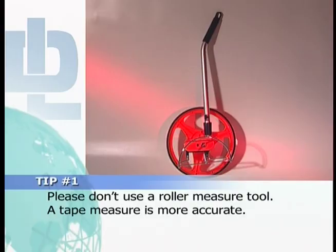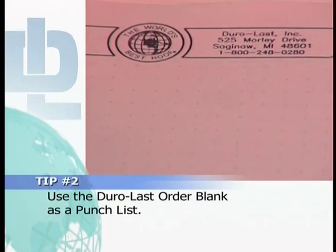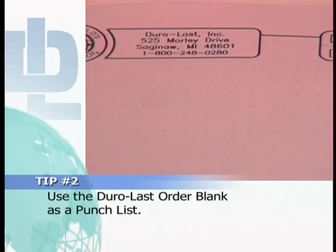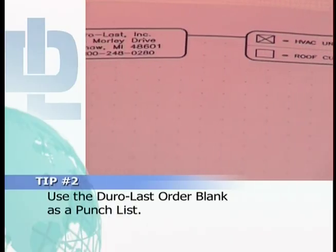you miscalculated square footage. Make sure that you bring with you to the job site the Duro-Last grid sheet and a Duro-Last order blank along with a couple of pencils. This is a powerful combination to accurately record what's on the roof. Use the order blank as a punch list so that you don't miss any items such as stacks, drains, curbs, or the size of fasteners that you'll use.